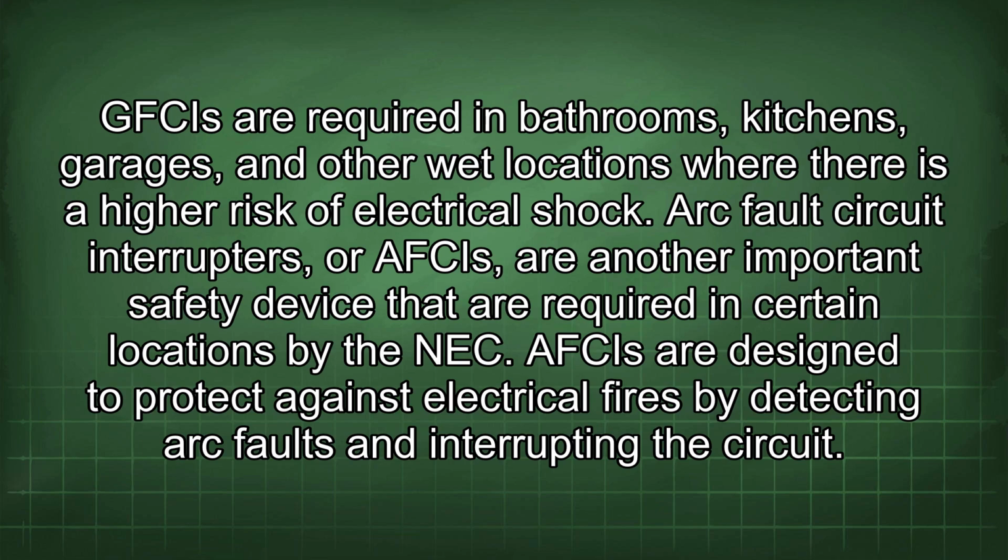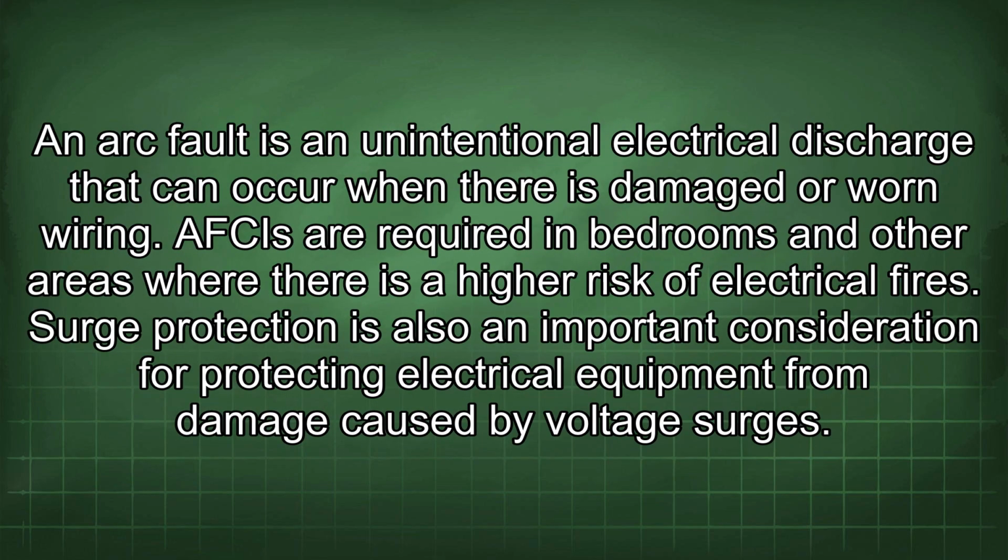Arc fault circuit interrupters, or AFCIs, are another important safety device that are required in certain locations by the NEC. AFCIs are designed to protect against electrical fires by detecting arc faults and interrupting the circuit. An arc fault is an unintentional electrical discharge that can occur when there is damaged or worn wiring. AFCIs are required in bedrooms and other areas where there is a higher risk of electrical fires.